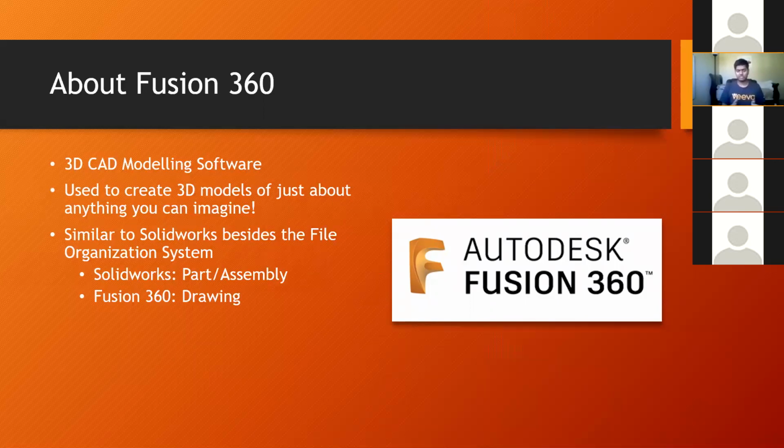However, Fusion 360 doesn't have this, and that's why I kind of don't prefer it, but you can still make it work. Fusion 360 has something called drawings, where you can create single parts and also create assemblies within the same file. So to organize that, it mostly comes down to your own file system management. You'd have to label a specific drawing an assembly or a specific drawing a part.